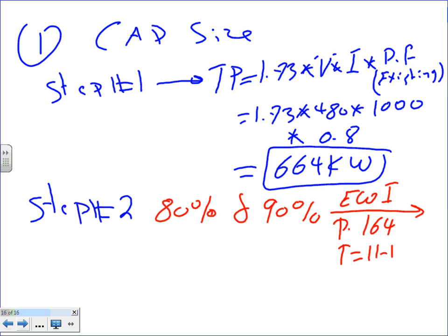You find a multiplier. If you guys look at this table I'm looking at, the power factor at the top is the corrected one, the one that I need to correct to. Can you guys see that? The power factor on the side is the original one. On the top, the columns are the corrected one. So can you find the multiplier from this table, the multiplier for an 80% and 90? 80 original, 90 correction. So don't forget that. That's 80 as original. This is corrected.